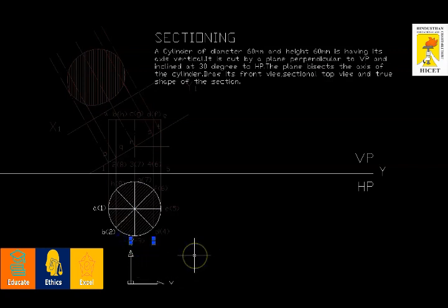See, a cylinder has two ends, right? So just imagine a cylinder, the top end, I'm dividing the circle into 8, okay? So each point I'm naming with alphabets, A, B, C, D, E, F, G and H. The 8 divisions I'm naming in alphabets. The bottom divisions, similarly, 8 divisions, I'm naming as 1, 2, 3, 4, 5, 6, 7, 8. So when I see from the top, I can see the alphabets, but the numbers will be hidden.